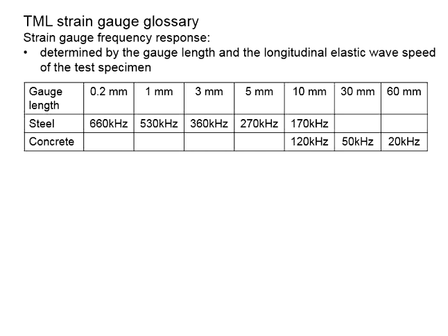This is to prevent the crack from bypassing the gauge during the measurement, which results in inaccurate measurement. In common practice, let's say now the maximum aggregate size of the concrete is 20 mm. We will use a gauge with the size of 3 times the maximum size of the aggregate, which is 60 mm.